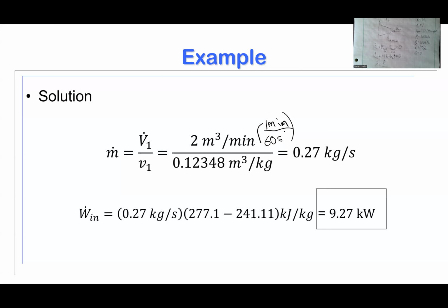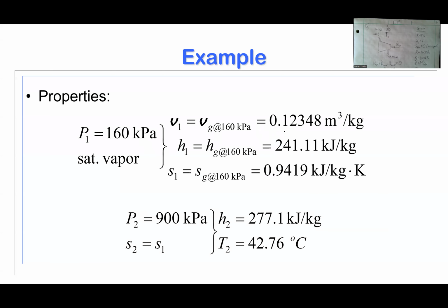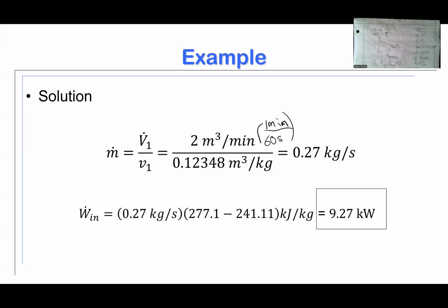So two answers there. The power input, that's the minimum power input. This gives us an idea. If you need something this big, this gives you a minimum amount of power input in order to achieve that. And it also gives you an idea of what the exit temperature ideally could be at the outlet. So if it's going to another heat exchanger after this in a refrigeration system, it needs to be in an environment where it can still lose heat at that temperature.